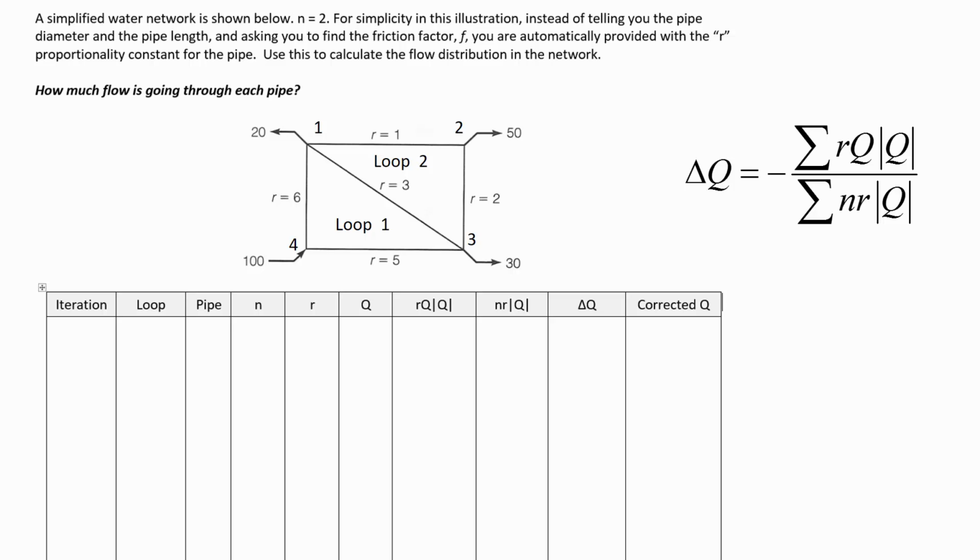All right, what about pipe 1, 4? What flow rate do I have there? Yeah, I don't have anything better from loop 2 than 49.24, and the same thing is true of pipe 3, 4. I need to have negative 50.76.